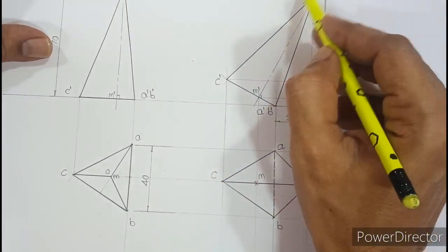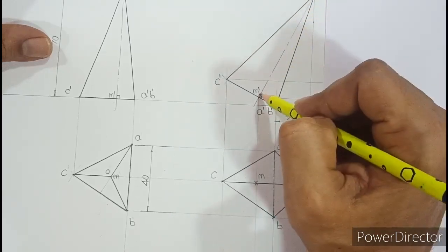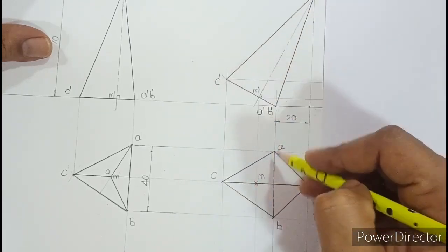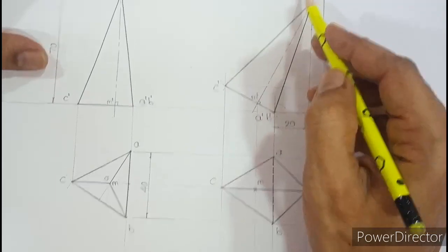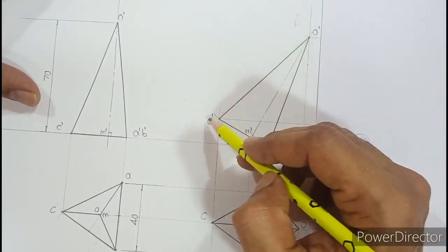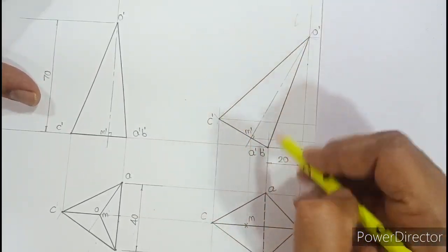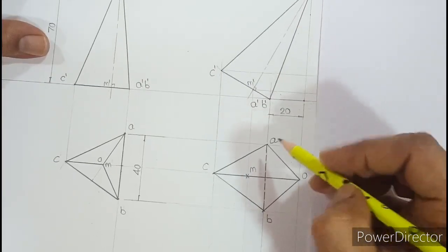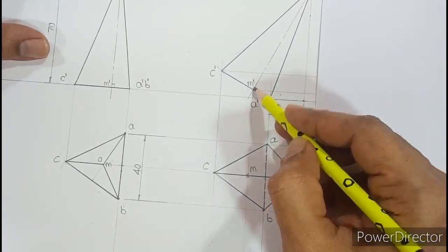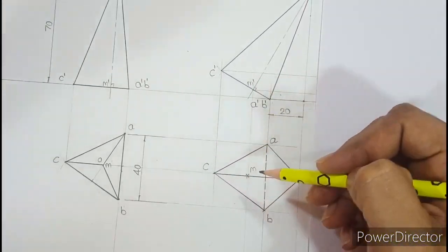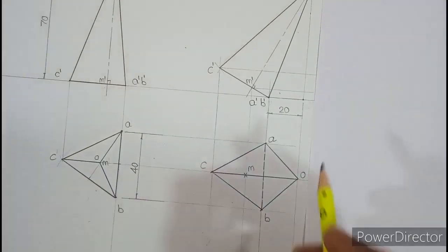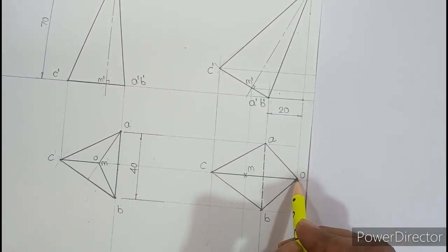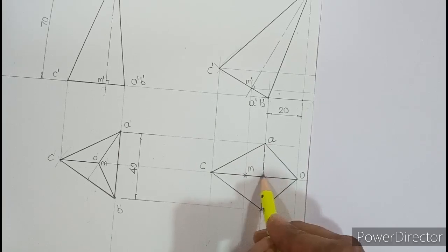Second, if you look from above, compare O with M. Because M is away, base is away, so AB will be hidden. Even if you switch on the bulb, you can see everything from C to O. You cannot see AB, and therefore AB is hidden. Finally, you need to mark the axis M. So remember that the horizontal distance from O till the hidden line AB, this is 20 mm.